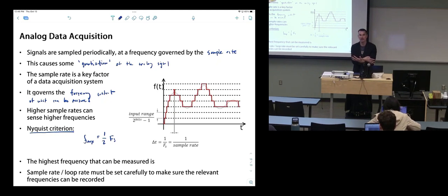So rather than seeing that sine wave, we'll see a downsampled version of that sine wave, which is also a sine wave. Something that existed at a much higher frequency, once it gets sampled, looks like a lower frequency. In order to prevent that, a lot of times people would add a hardware filter to block out any frequencies above the Nyquist criterion. That is a level of detail that I can speak to, but wouldn't require you to know.